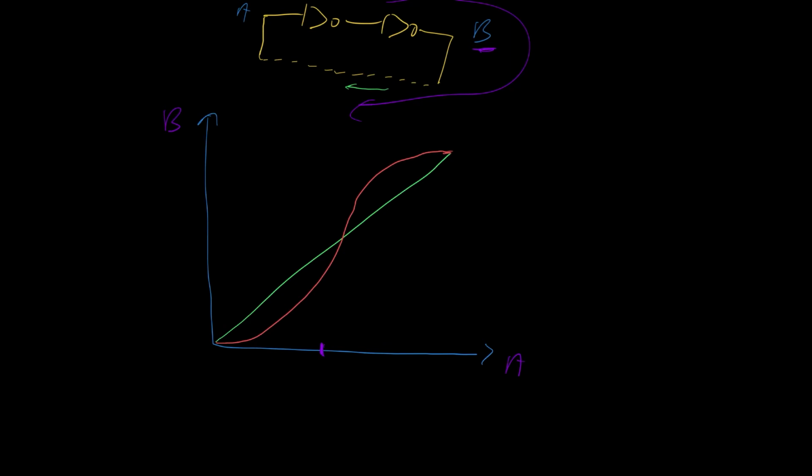By definition, that's the red curve. So I go straight up here, and I find this is the voltage I get at the output, if this is the input voltage. So now I want to know what happens if this output voltage is fed round and becomes the input voltage. Whatever value this is, and we find that out by going across here, if this voltage were, for example, 2 volts, then I'd want to come down to this axis here and find 2 volts and repeat the process.